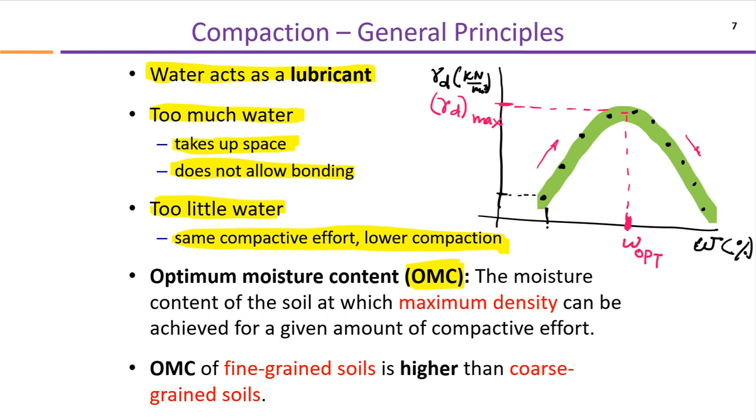Okay, so let's say this is the optimum water content. The left side of this curve is called dry of optimum, and this side is the wet of optimum.